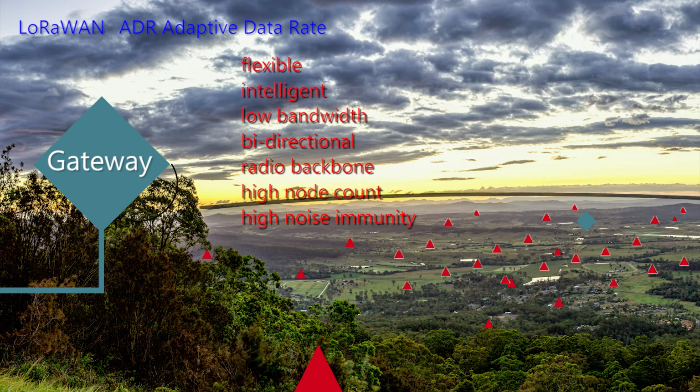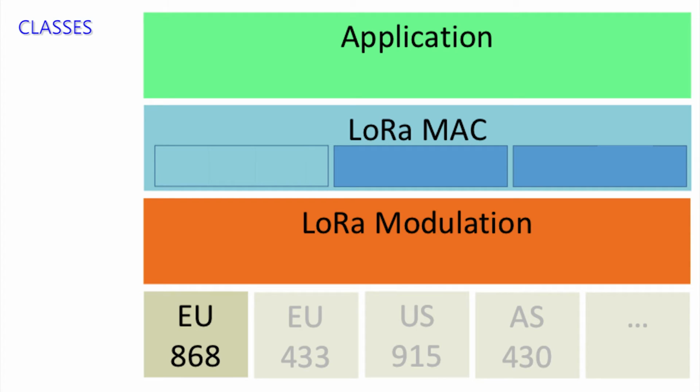Finally, nodes can be classified into three types, referred to as Class A, B, and C. All devices begin as Class A, but may convert to B or C once they've joined the network. Class A allows the node to shout out a request to join the network regardless of the state of any other node that already may be communicating. It just interrupts rudely, possibly destroying any existing communications. In Class A, it can only receive for a very short period after its transmission. Historically, this behaviour is referred to as Aloha and is typical of early networking schemes that predate systems like Ethernet.